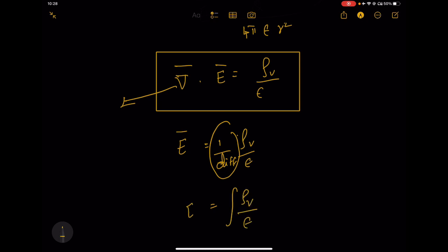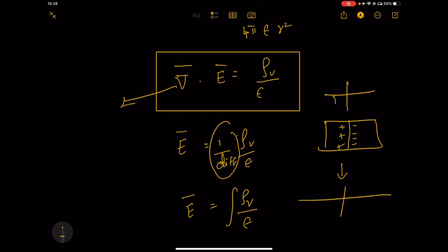If you remember one of the problems, we were talking about the relation for a charge distribution that was given for a diode, and we were interested in knowing what is the electric field for it. To get the electric field pattern, we had a charge profile like this. For this charge profile, what will be the electric field? The electric field will be like this. Why is it becoming like that? When you integrate a step, it becomes a ramp.